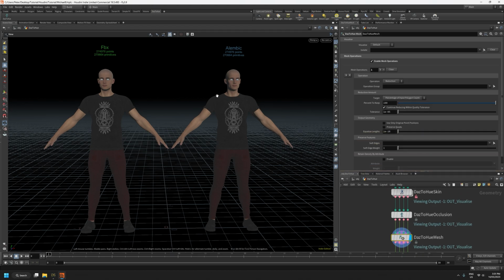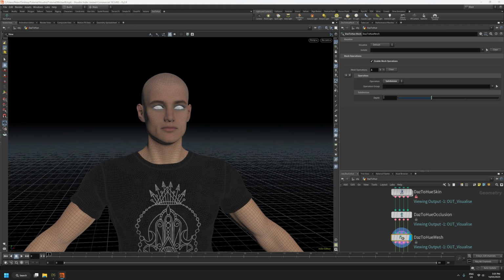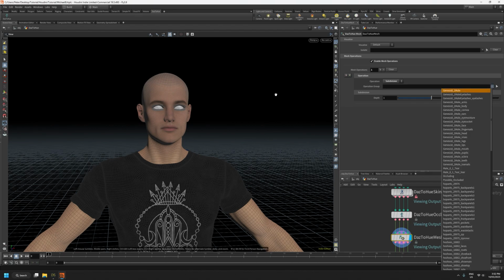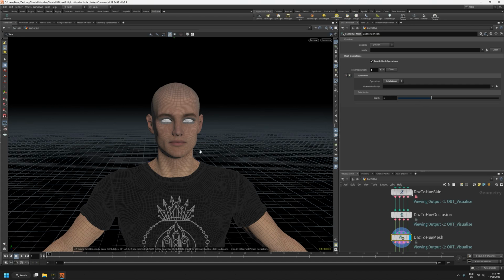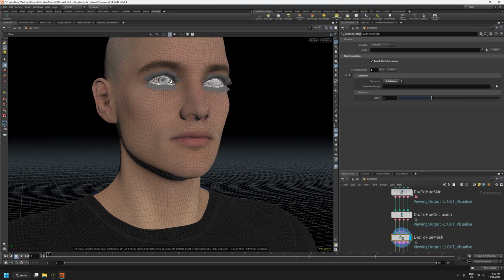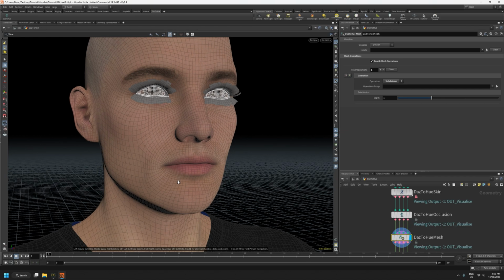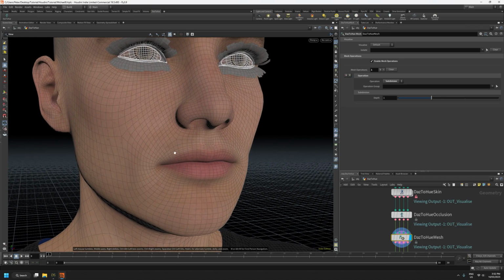So we'll have a quick look at subdividing first. It doesn't have many options other than the subdivision depth. What we do need to do is tell it what we want to subdivide. And again, we could do the entire character and its clothing, or we could do just parts of the mesh. When performing subdivision operations, however, it's important that you select a continuous geometry shape or continuous part of a geometry. By that I mean, for example, you wouldn't want to just subdivide part of the character's face, or you will end up with a situation where the vertices don't align anymore.